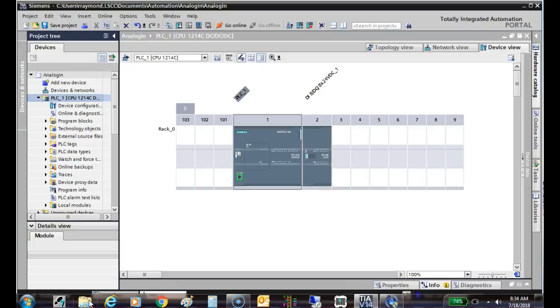And this is one major reason why your meter does not use legal scientific notation. So as soon as it got up to 199.9 ohms, it would range up to K. And then it might show 0.253 K, and everybody wants to put that down when it's actually 253 ohms, right? You understand? So our PLC A to D converter, that's exactly what it does.